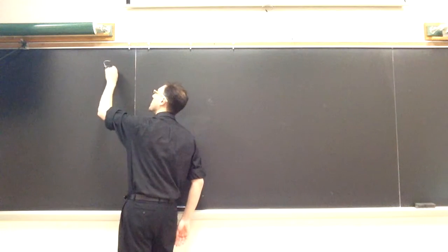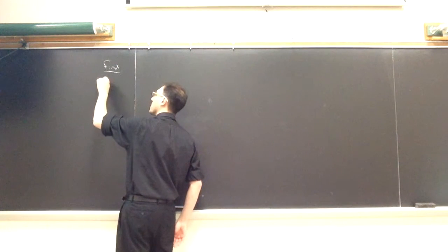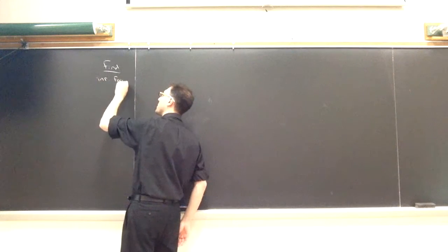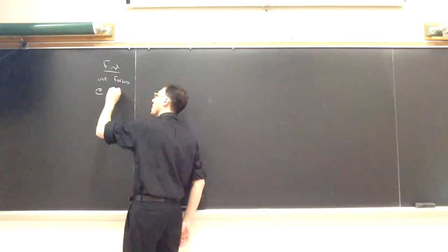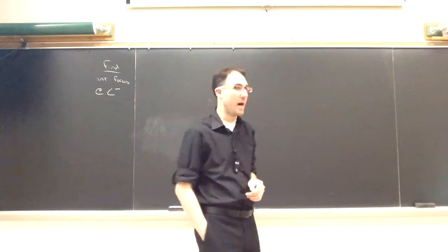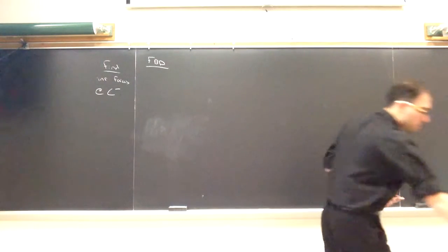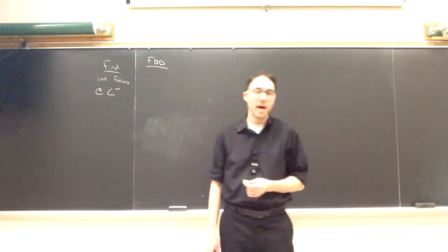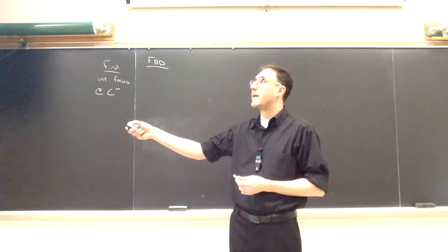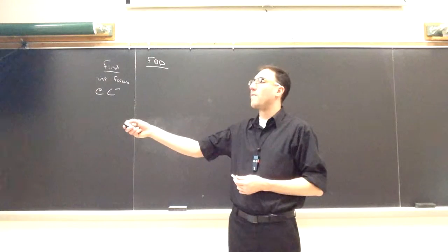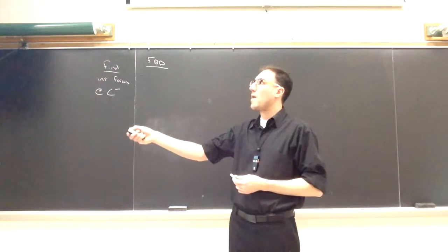Find internal forces just to the left of C, or as I designate it, C minus. Create a free body diagram. If we picture the cut we will have to make here through point C, or just to the left of point C, we'll have our choice of everything to the left of it or everything to the right of it.